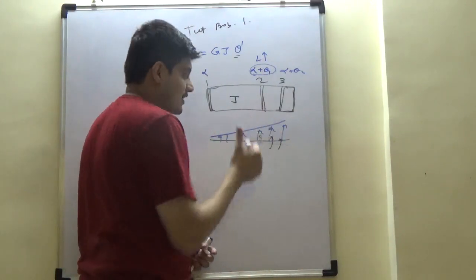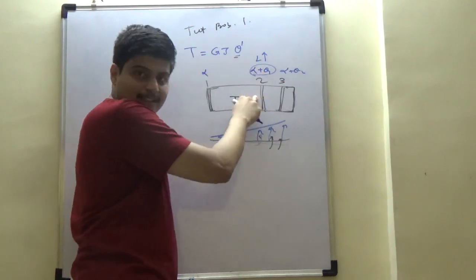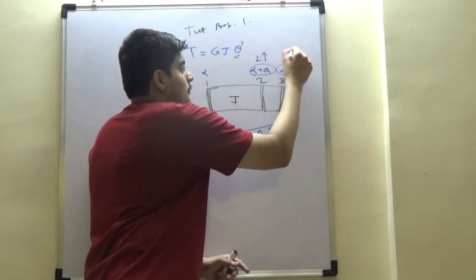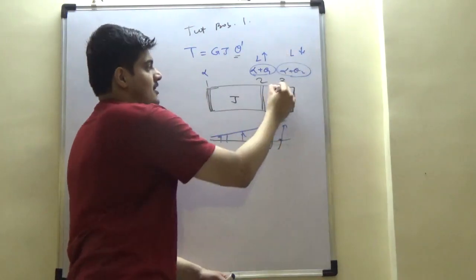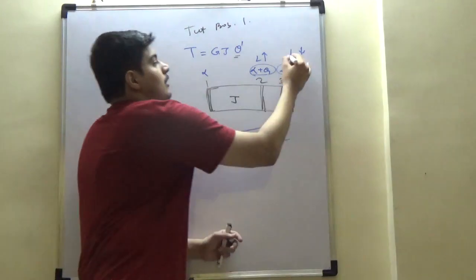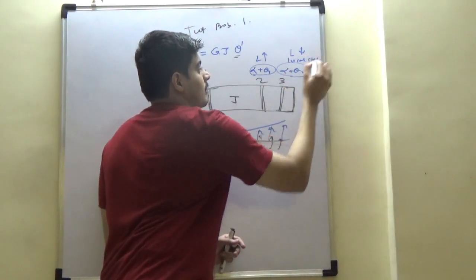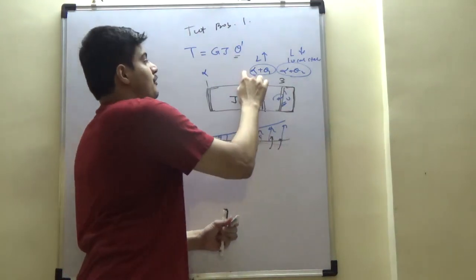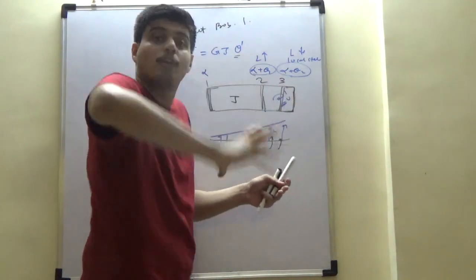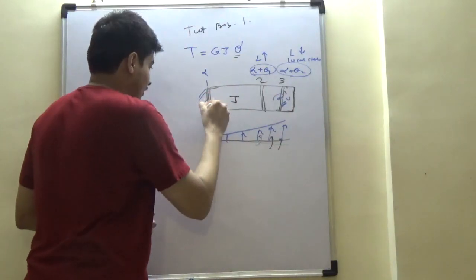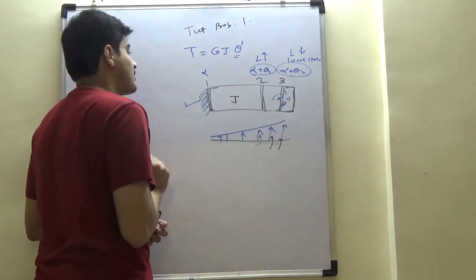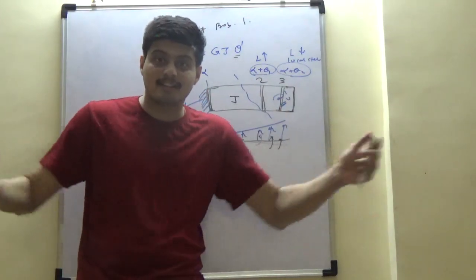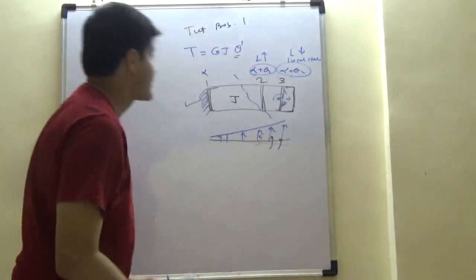It increases towards the edges slightly, further enhancing this tendency to twist further, and at some point when theta becomes large, lift drops drastically over those sections because of stall, local stall, and then these vortices, eddies, get formed. If sufficient energy is built, this may cause resonance, increased tension here, and this energy dissipation is going to cause the wing to get fractured. That's the outcome of aeroelasticity.